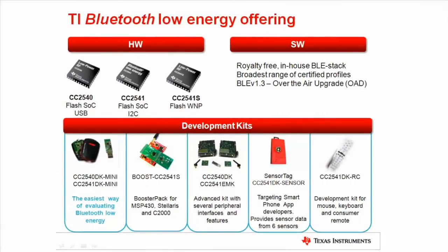TI has the broadest offering of Bluetooth Low Energy silicon, software, and development kits. The Bluetooth Low Energy parts are available as devices with USB or I2C interface, as well as the CC2541 network processor that makes it very easy to interface to existing application processors in the systems. The TI Bluetooth Low Energy stack was the first to receive Bluetooth certification in 2010 and offers the most complete package of features, including over-the-air upgrade capability.